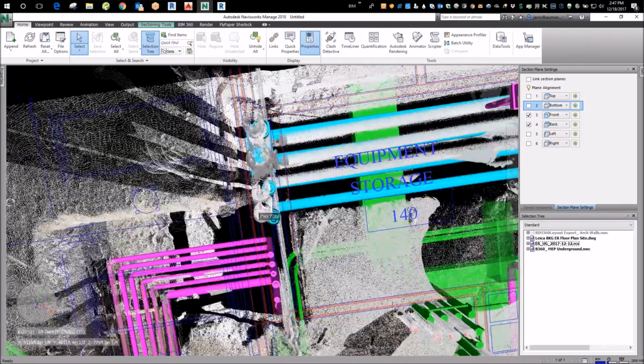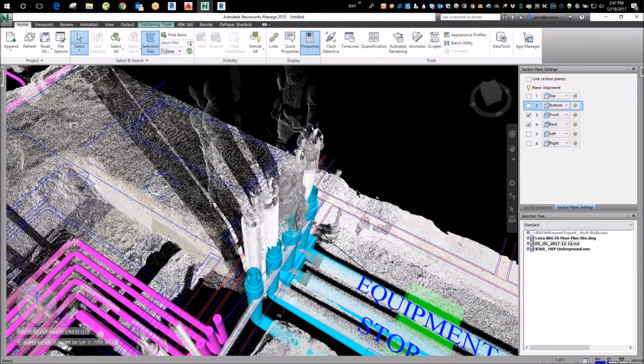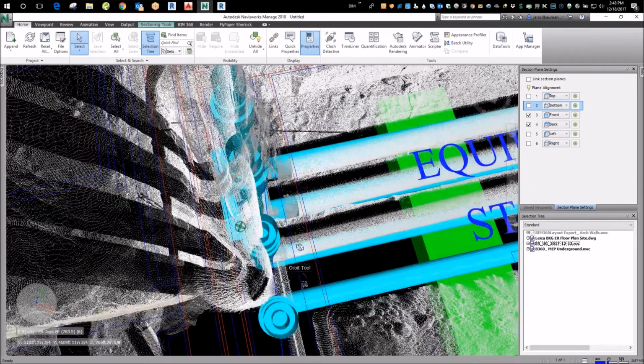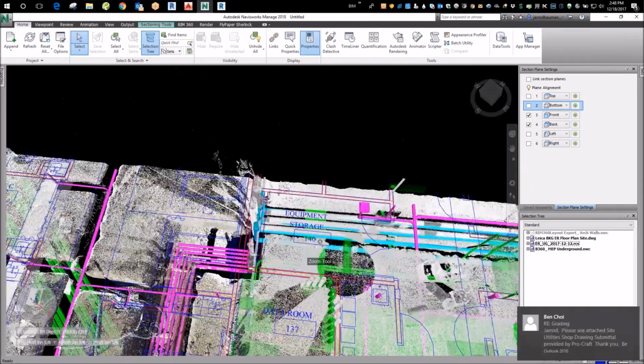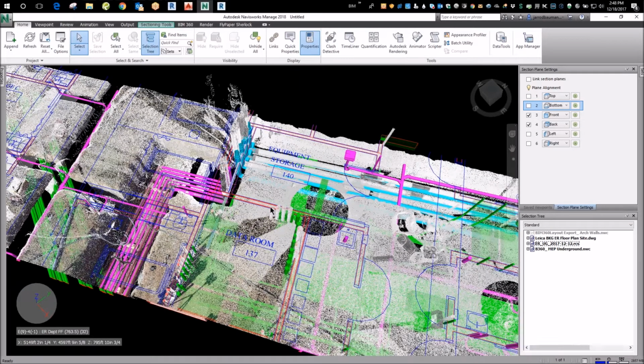Right, so these guys have all produced shop drawings. This is an Oshpod job. These BIM models have everything, every seismic in it. We're pushing them to a very, very high level of detail on this one. And so their shop drawings are all coming from the BIM, fully dimensioned. So these guys should be attempting to hit these locations. So you can see how quickly, a few hours out in the field, it's possible to turn this around in a day's time, right? We come out there, we shoot it, we register it, we put it together the next day, give it back to you guys, all overlaid, ready to go.